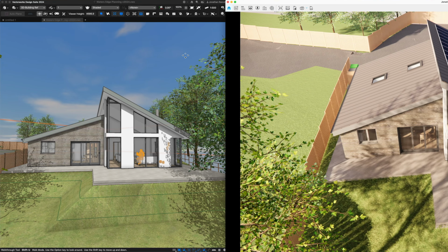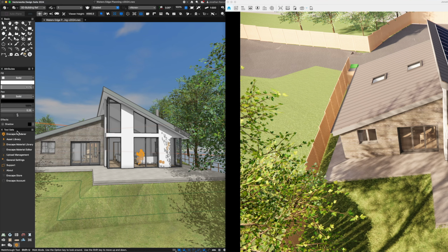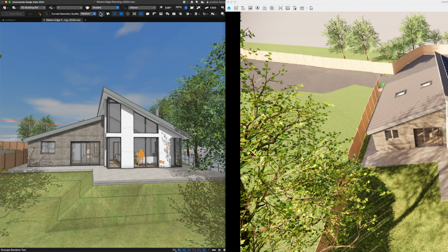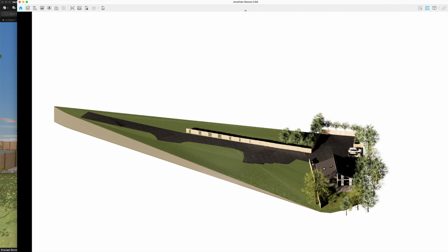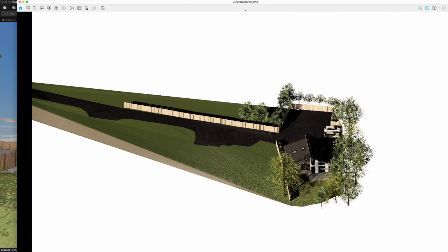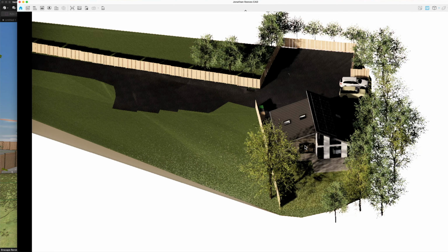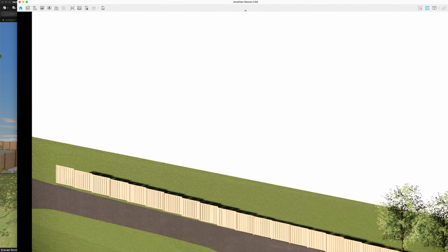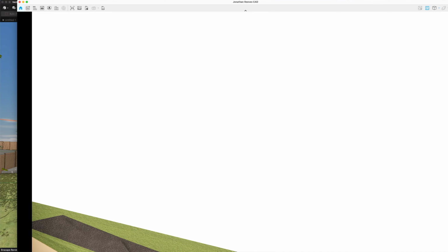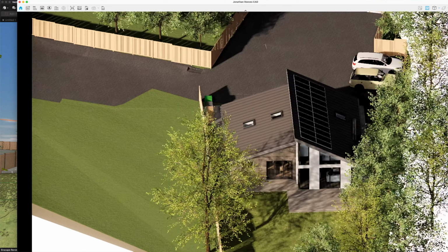Now, at the moment, I'm in Vectorworks with my linked view set up, my synchronized view. So if you do have your synchronized view set up in your CAD software, you might just need to unclick this. And what that will enable you to do now, you'll notice, is go to the projection settings and actually change it over to orthogonal. The really nice thing about orthogonal projections is they're very architectural in that you get these nice axonometrics or even elevations and things like that.